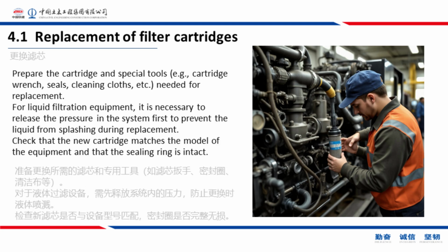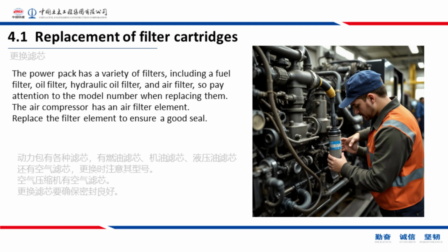PPT 36. 4.1 Replacement of filter cartridges. Prepare the cartridge and special tools, for example, cartridge wrench, seals, cleaning cloths, etc., needed for replacement. For liquid filtration equipment, it is necessary to release the pressure in the system first to prevent the liquid from splashing during replacement. Check that the new cartridge matches the model of the equipment and that the sealing ring is intact.